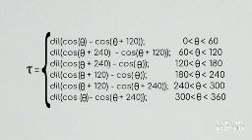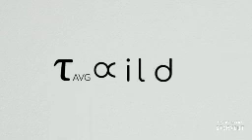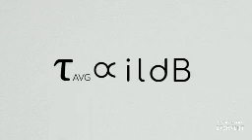But where does this leave our torque function? If we actually wrote out our equation as a function of rotation angle, it's a 6-part piecewise function, where our output torque fluctuates about 14% periodically throughout rotation. This fluctuation is referred to as torque ripple, and we're going to talk about it a whole lot more starting around episode 8, but for right this second we're going to ignore it. If instead we calculate the average torque across a revolution, we find that our torque is proportional to the current running through the motor, the length of the motor, its diameter, and the magnetic field present.